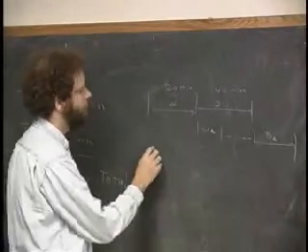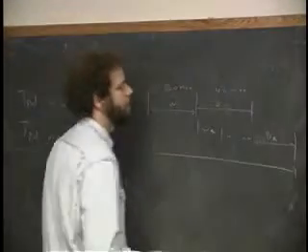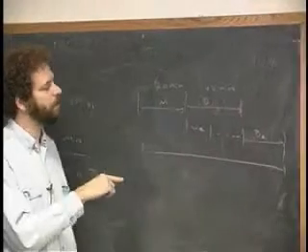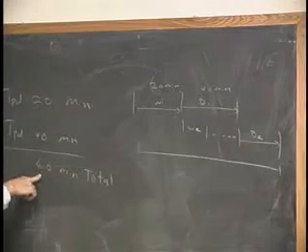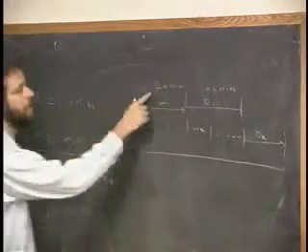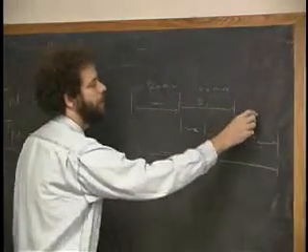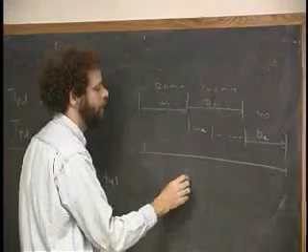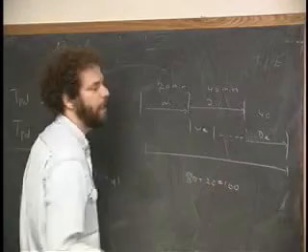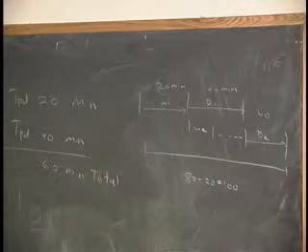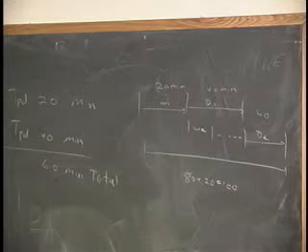So the total amount of time that it's going to take doing it the smart way, rather than being twice the propagation delay of the whole circuit, which would be 120 minutes, is going to be 20 plus 40 plus another 40, which is 80, plus 20 equals 100 minutes. So we have saved 20 minutes off the time to do this whole thing.